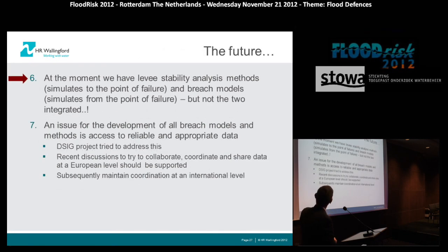Two last points. And this goes back to the discussion that we were having on Myron's paper right at the start. At the moment, we have levee stability analysis methods and models, and we have breach models, but the two never meet. You either say it's about to fail because I've done my finite element analysis and it shows failure, and then you don't predict breach, or you say it's failed and this is what's going to happen when it breaches. We should be putting the two together.